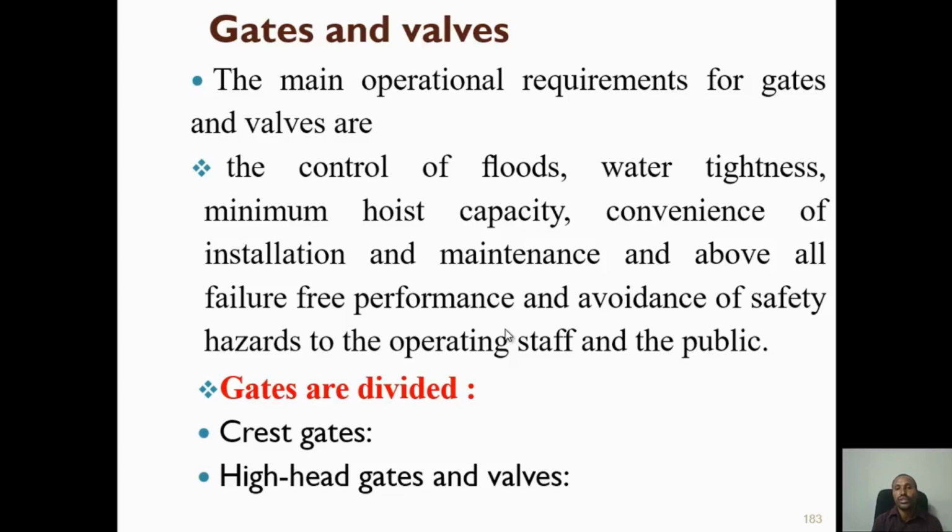So the requirements are control of flows, water tightness, minimum hoist capacity, convenience of installation and maintenance, and above all, failure-free performance and avoidance of safety hazards to the operating staff and the public. So for control of flood and water tightness, you can provide gate valves. Gate valves are divided into crest gates or high head gates and valves. Sometimes radial gates, crest gates, rectangular gates, you can open and close and control accordingly. So gates and valves are important.